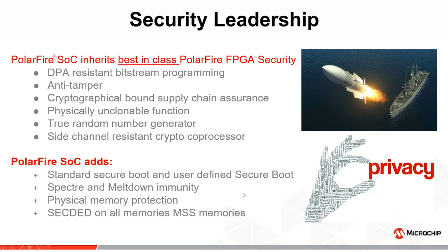Another aspect I'd like to emphasize is our security leadership. PolarFire SoC inherits features from the PolarFire FPGA in terms of security. So it has features such as DPA resistant bitstream programming, anti-tamper. So we have capabilities to monitor voltage, frequency, and temperature, apart from implementing an active mesh to check for tampers in your system.